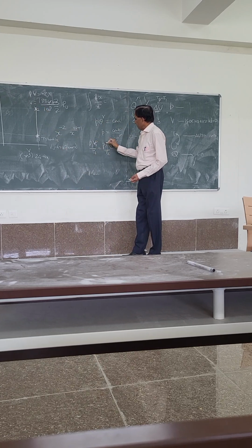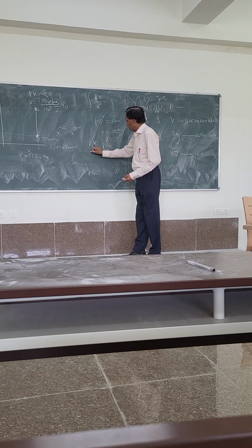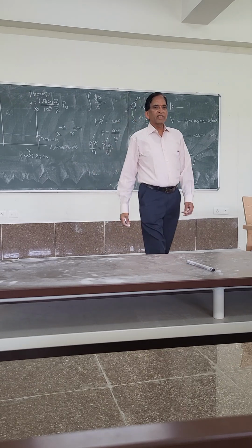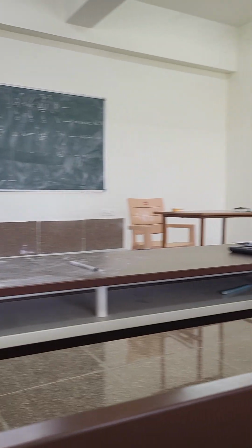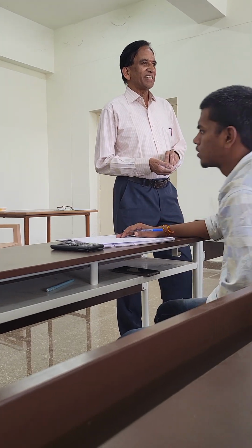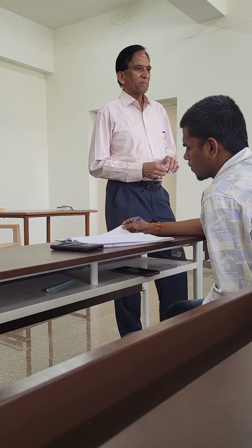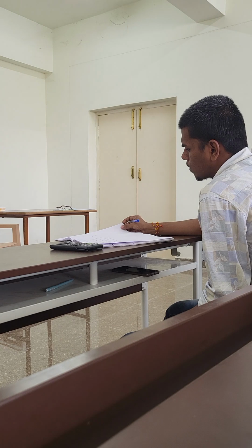So here V1 and V2 are the same. You know P1, you know P2, you know T1. Find out what T2 is. Temperature low. P2 is 8 bars, P1 is 1 bar.